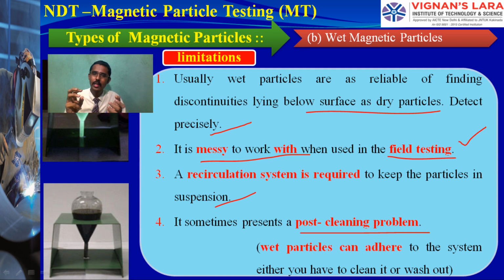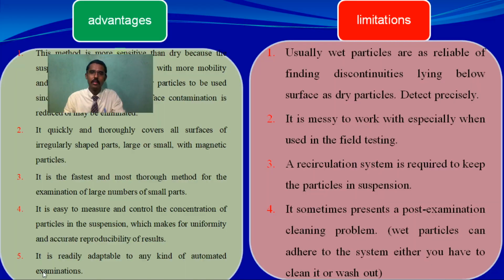These dry powders are sticking at a specific point, but wet particles are spreading, and it is already wet. Definitely it will stick on the specimens. For inspection purposes, it is uniform. After inspection, we have to clean. During cleaning, it may create some difficulties because it is adhering over the specimens. So this is how some of the limitations are there for our